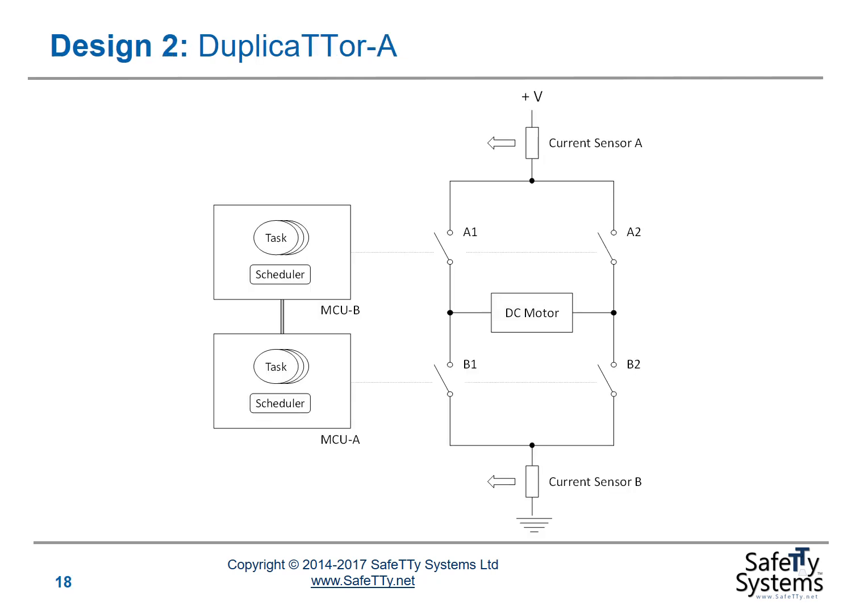Our second option, of course, is to use two separate microcontrollers to do this. Again, personally, I'd have a higher degree of confidence in this dual microcontroller arrangement because we've got a greater level of protection against common cause failures in this type of design.